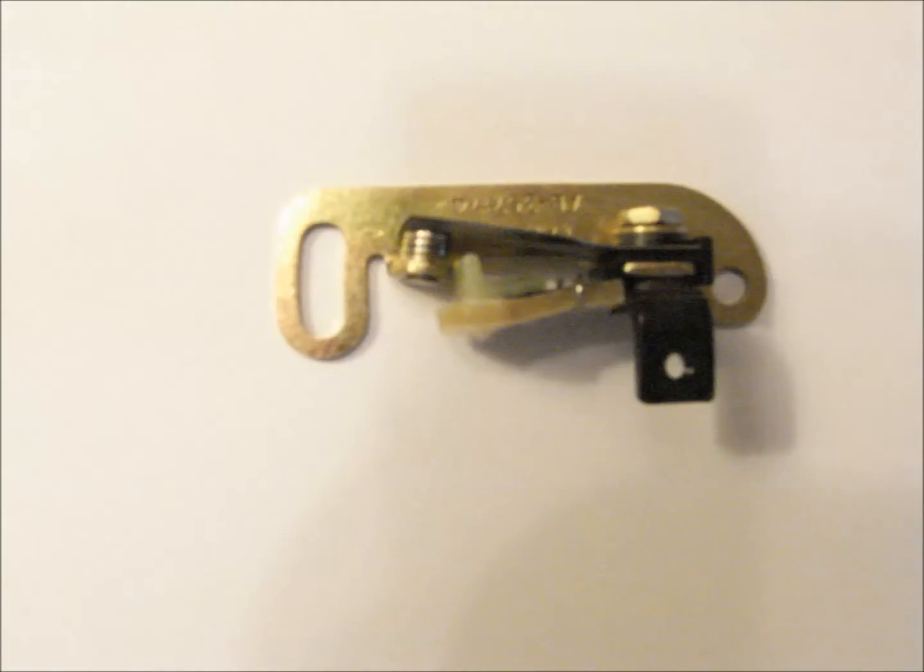The oil seal is pressed into the magneto housing and the rotor passes through it to connect to the engine drive. The oil seal's primary purpose is to prevent engine oil from entering the magneto housing. The points in the system open and close the path to ground from the primary coil. This causes the primary coil to charge when the points are open and discharge when the points are closed.